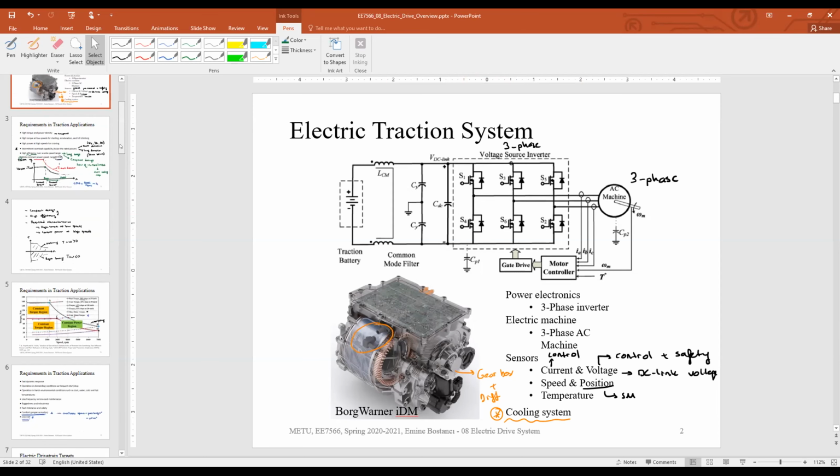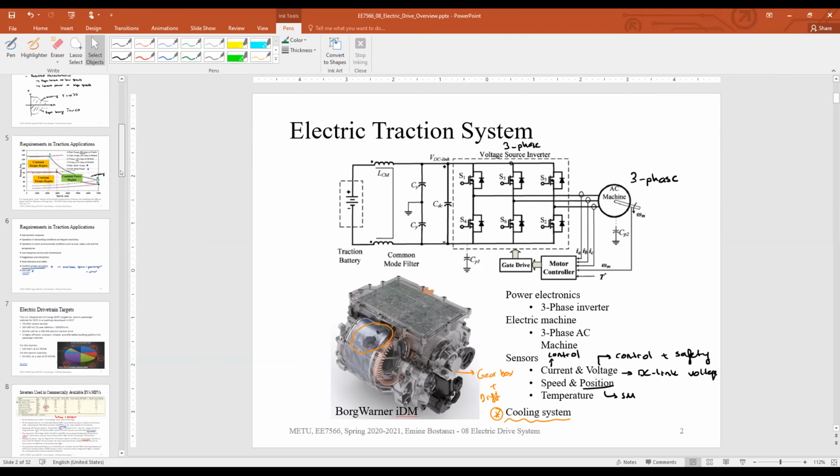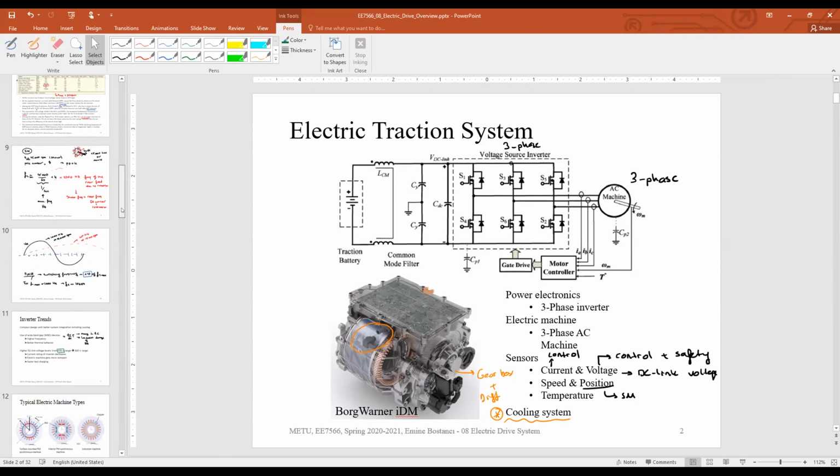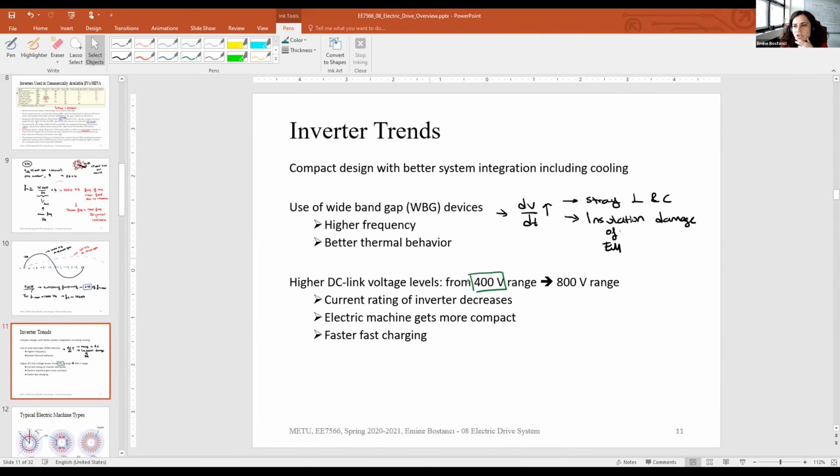I think, wasn't it related to the voltage of IGBTs? Exactly. So what is the voltage rating of our available IGBTs on the market? 650, something like that. Perfect. So there are ratings with 600 to 650 volts, or now I think there are 700 to 750 volt ratings too. And the next rating is the 1200 volts.